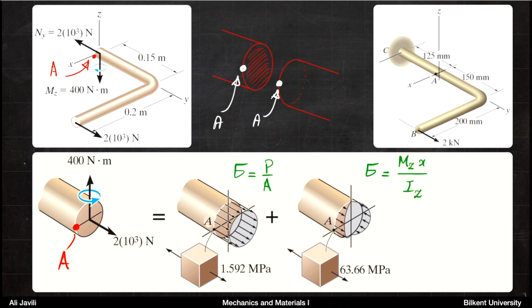Here the distance from the z-axis is the coordinate x, and if you think of the signs, you can imagine that on this portion you would have compression, and on this portion you would have tension. Now on the portion that you have compression, x is actually negative, and on the portion you have tension, x is actually positive. Remember, this is the way the x coordinate is set. So that means you do not need a minus that you would usually have here. So the sign is correct as it is, and then from that formula you can calculate again the stress state